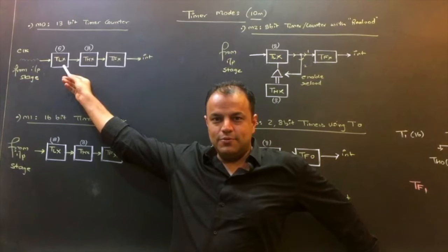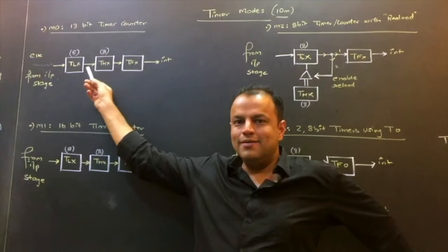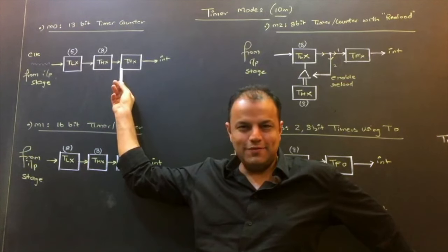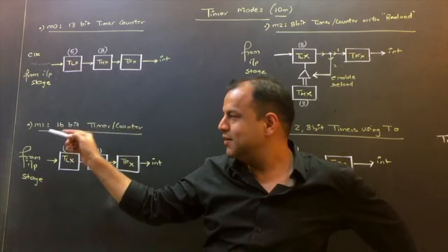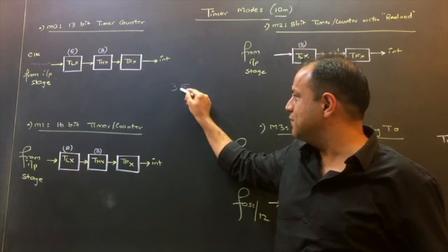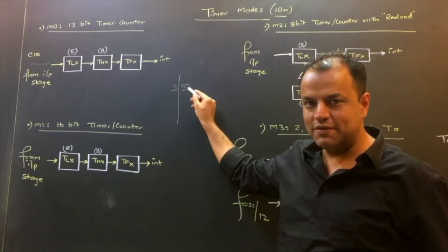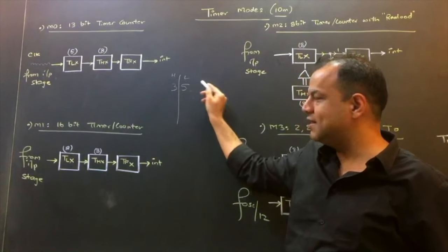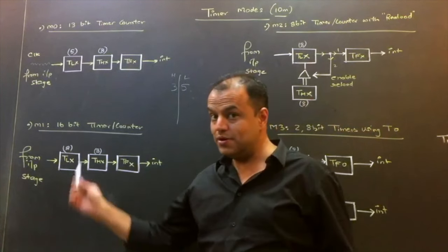I've written lower byte over here and higher byte over here. That's how it should be written. Students write it the other way around. Not their fault. It's a normal tendency. I have a number 35. 3 is the higher nibble, 5 is the lower nibble. So we always have a tendency of writing the higher on the left and the lower on the right, because that's how it is. But not in this diagram.